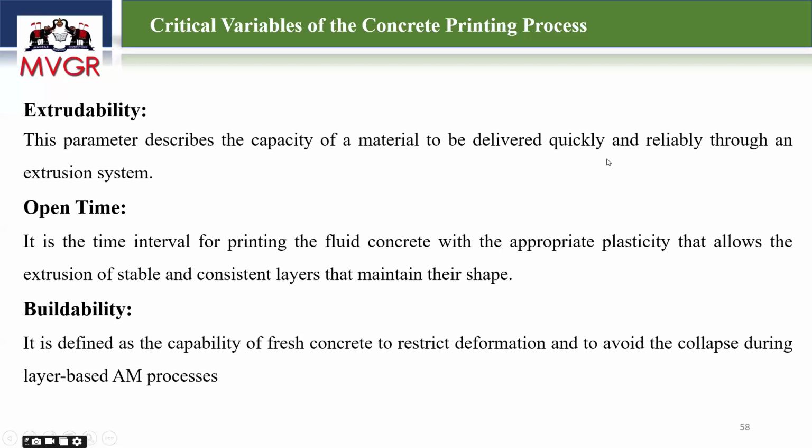It has to extrude through the nozzle, and it should have an open time. Whenever you want to print and pass that material for construction, it should easily solidify. It has to gain plasticity easily. Only then can we have a short open time. That open time must be as short as possible. If it takes a lot of time, you have to wait until it gains that plasticity. So we need to reduce this open time.